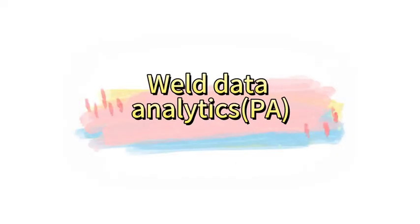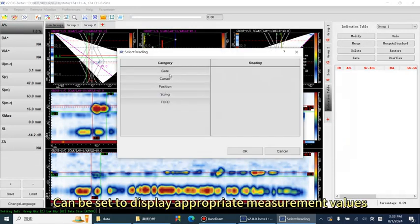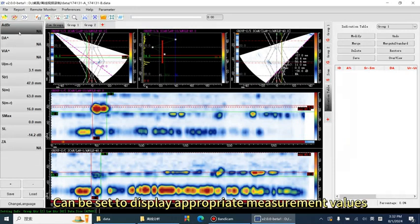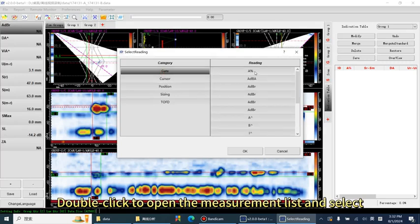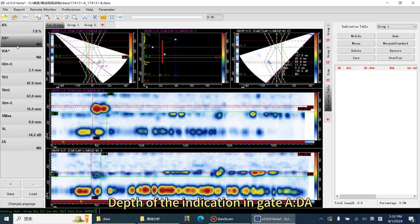Welding Data Analysis in PA. After opening a welding data file, when first analyzing welding data, we can set it as needed to display appropriate measurement values. Double-click to open the measurement list and select commonly used welding analysis measurements. Peak amplitude in data, A%. Depth of the indication in data, DA.